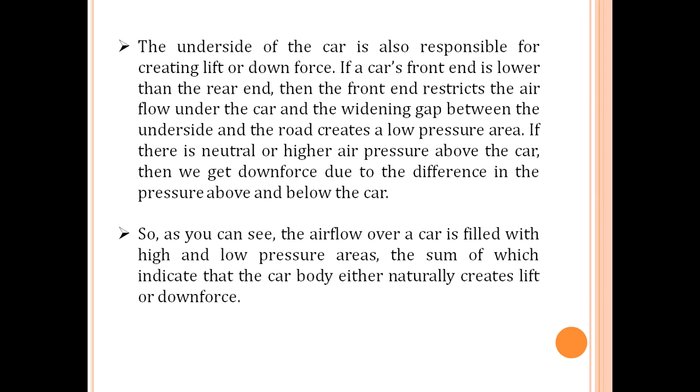If there is neutral or higher air pressure above the car, then we get the downforce due to the difference in the pressure above and below the car. So the underside of the car is also responsible for creating the lift or downforce.